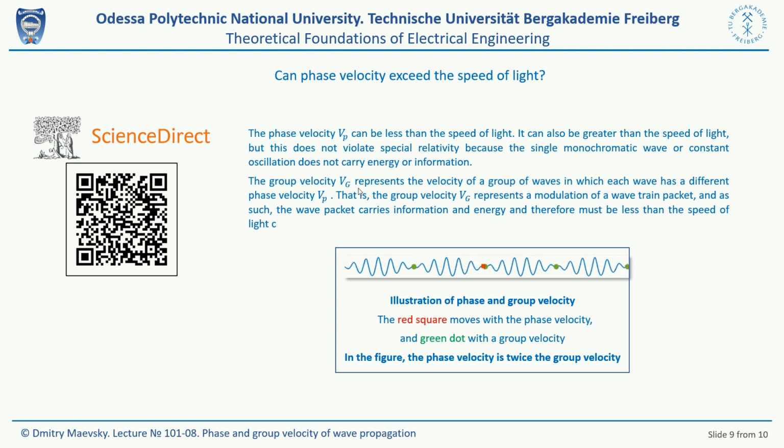For example, earlier we talked only about the direct voltage wave, but the voltage wave itself cannot carry electromagnetic energy. Remember, energy, and with it power, occurs when voltage and current act simultaneously in a circuit.